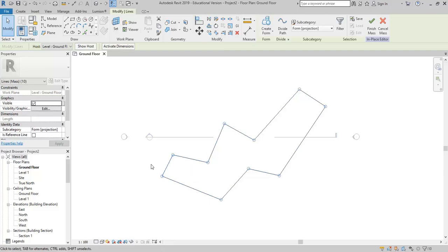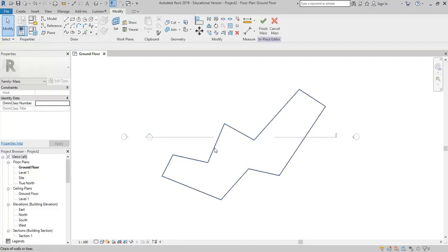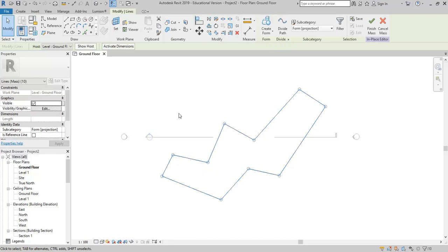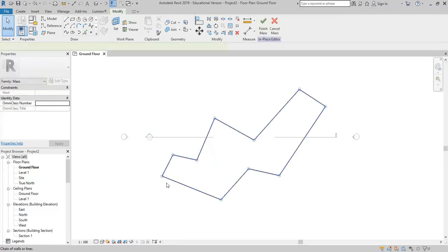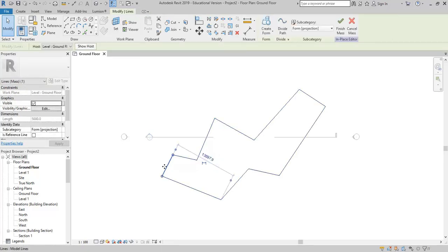Right, so if this was an extrusion and I drew some lines, when I select any of those lines, they'd come up individually. But you can see here, it knows those are connected, so I select it and it selects the whole shape. So if you just want one line, the easiest way is just to select again. And now I've got one line there and I can adjust that. Okay, so again, select the whole shape and then click again to select one line. Tab works as well.